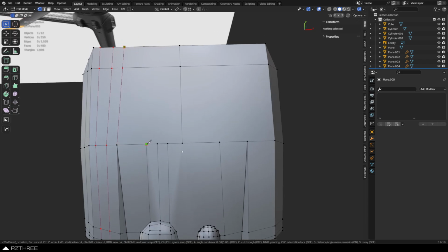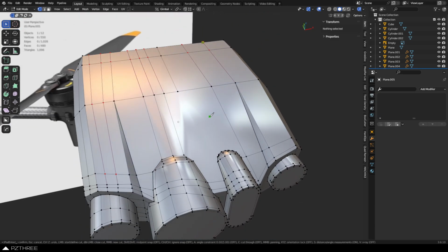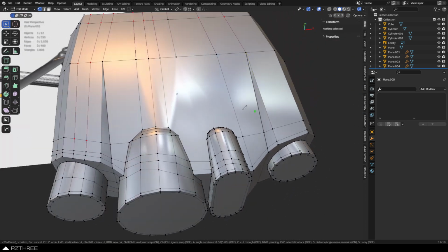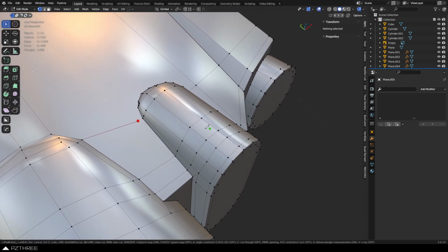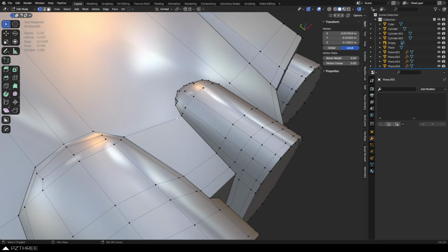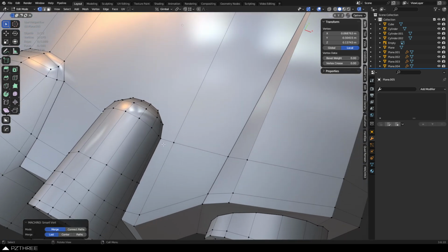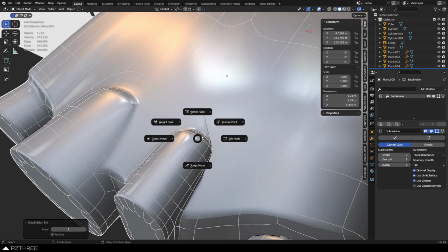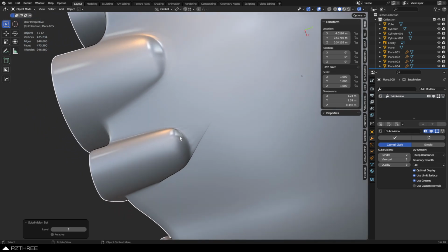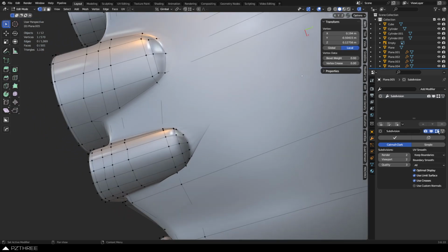Now this is kind of a slow way of doing it in general. So a lot of guys that are going to create models that are just game mesh, right? Or they're baking mesh, so they can bake something onto a low poly model. You don't necessarily do all of this. You can do little cheater methods where you still use rather bad n-gons even. But if you use them on flat surfaces, it doesn't really matter, because if we start subdividing, you can see this is falling apart here. This is bad shading. You couldn't bake something like that, right?